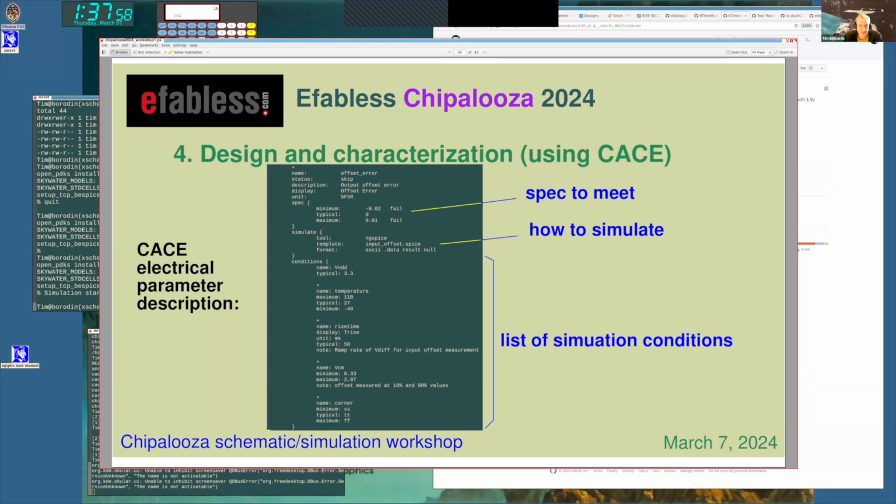It's fairly straightforward. In the specification, I've said, all right, for this particular electrical parameter, there's perhaps a minimum value limit, a maximum limit, a typical value. Normally, you'll have something like a requirement that the maximum value is the absolute limit. If so, then if you exceed that, then you're failing spec. So I would put maximum for the maximum value, put the value in here. In this case, it's measured in percent full scale range.